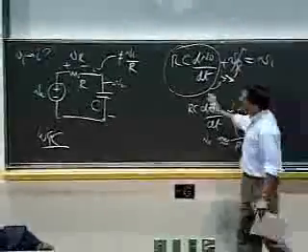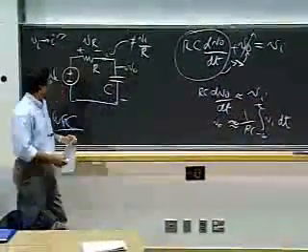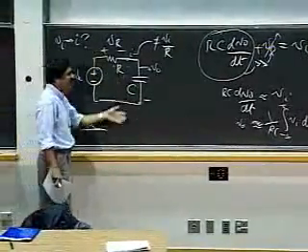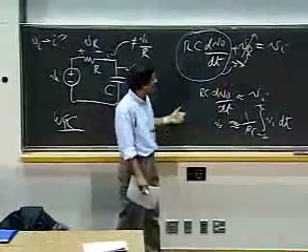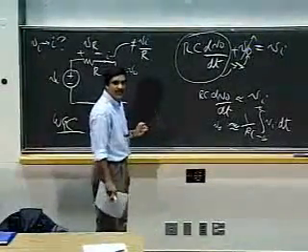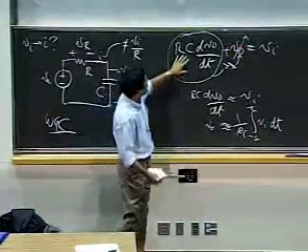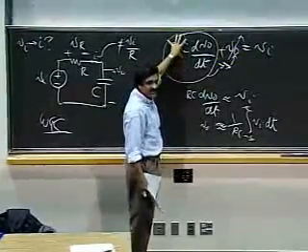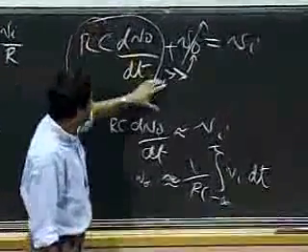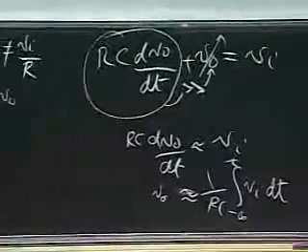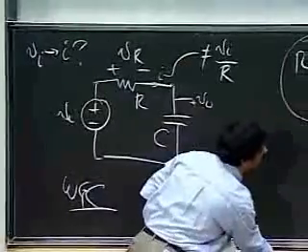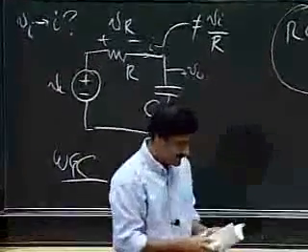I'm on this wild goose hunt here, trying to find a way to get a current from a voltage, which I can then feed into a capacitor. So this was one thing I knew, but this is not what I want. But it does turn out to be what I want when V naught is very, very small. So I see some glimmer of hope, but not quite. When I make R and C very, very big, with a huge time constant, the voltage V naught looks like an integral of VI, but only when I have a very huge time constant. So I give up on that tack.